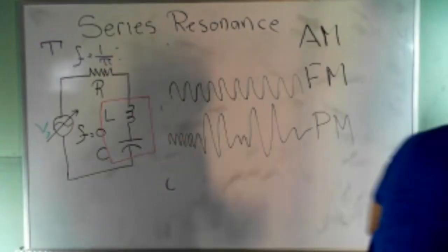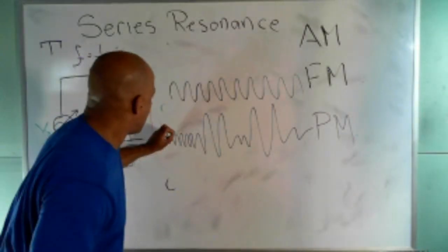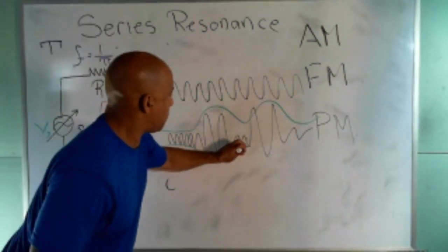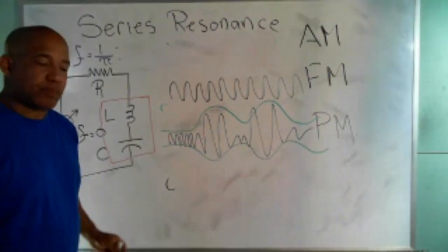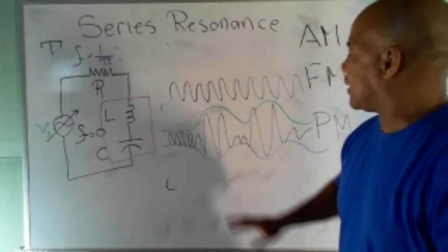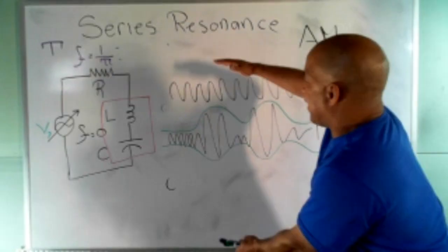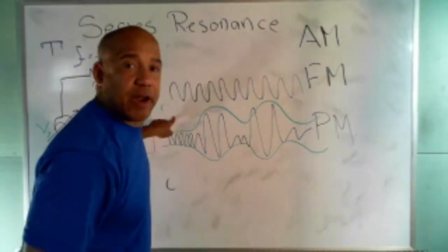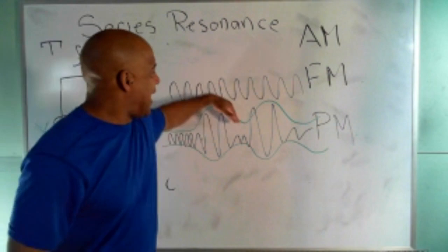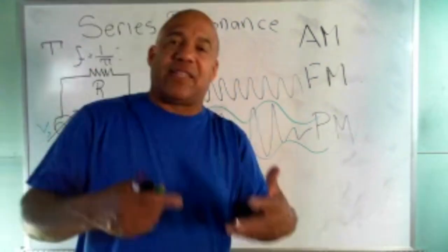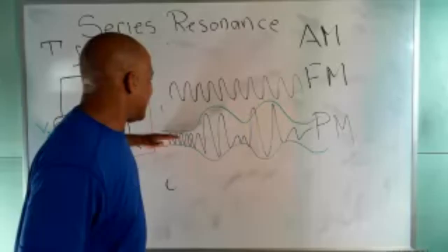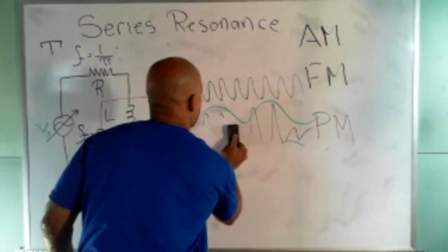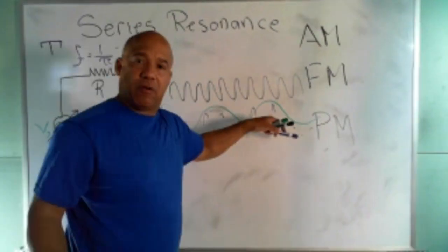And if you look, watch this. You see that? And that. Well, in radio electronics, communication electronics, this is called an envelope. So this varying is in direct proportion to my voice, but what you've done is at the top of the carrier and the bottom of the carrier, you created two other sound waves. And those sound waves are the audio that I just put on the frequency. I modulated the signal, so what I can do is I can take the carrier out, and I'm left with this. I take the carrier out, I'm left with that low frequency signal, which is the audio from my voice.